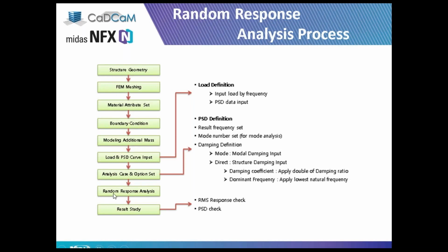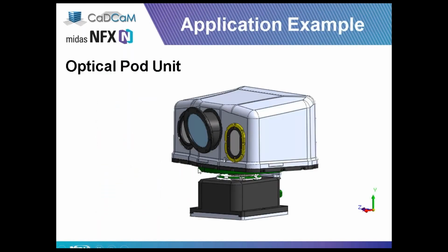We define the random response analysis in Midas, and then we get the results and study them. We can get the RMS response check from the point of view of stress and deflection, and we can get the response of PSD at each point of the system.